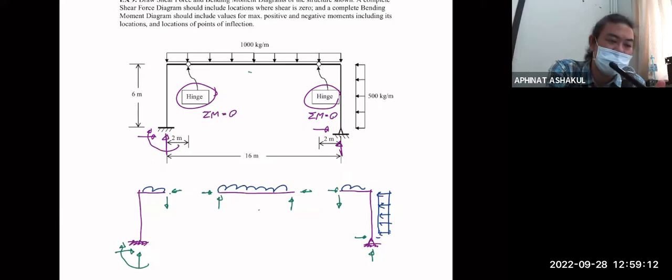This piece that you cut the free body diagram through the internal hinges, this piece is definitely symmetric. So when this is symmetric, it means that you can solve for these 2 unknowns right away because they're symmetric, right? So that would be a good place to begin. We have 2 meters from the hinge, so that means this piece is 12 meters long.